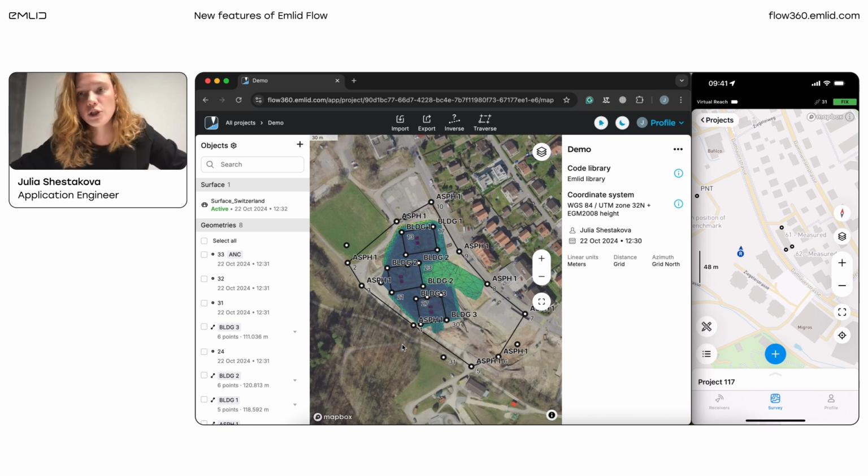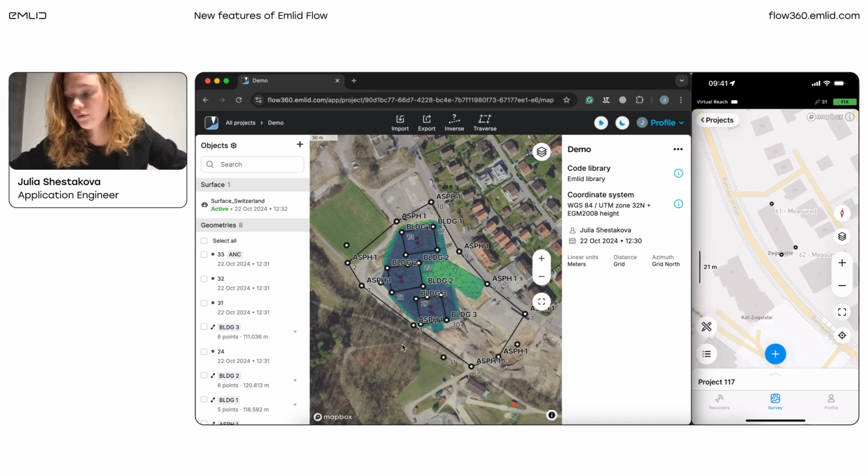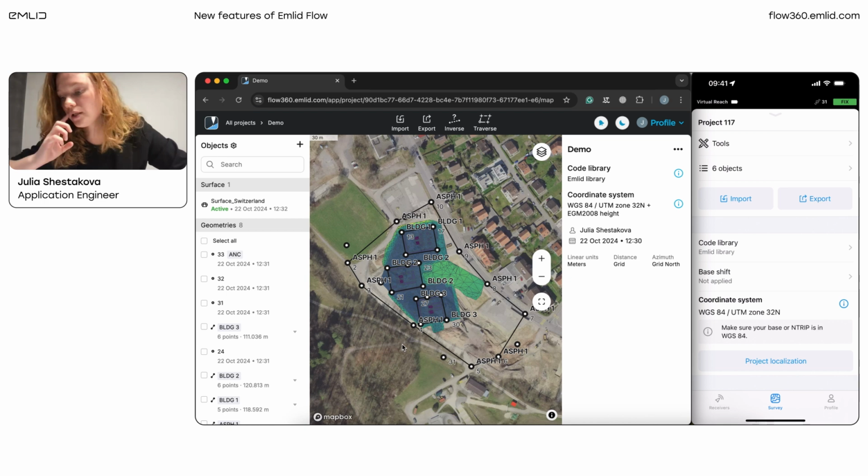For that, you need to, again, place your base, connect your rover to the base, and measure the points with the coordinates, the points for which you know the coordinates in this coordinate system you'd like to work with. In my case, I have 3 measured points. And what I need to do now is to create pairs. I already have imported the points with known coordinates here.